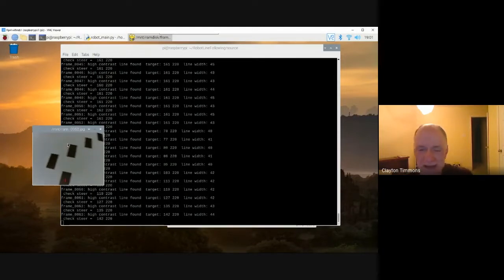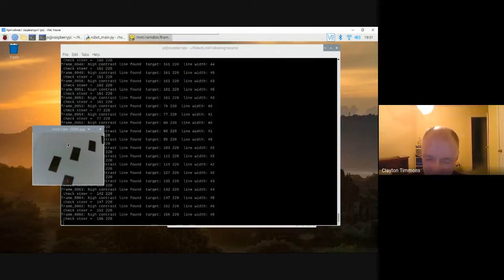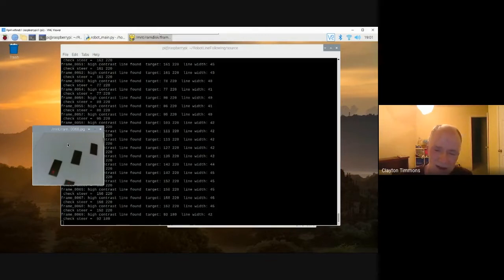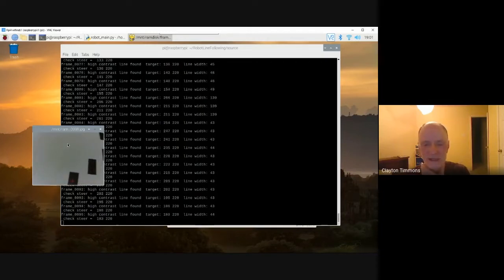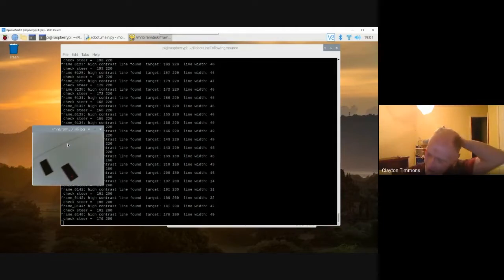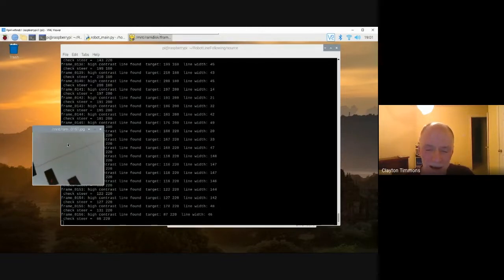And I'm very curious because I'm seeing, a lot of getting this to work correctly is the steering algorithm or tuning. When I see this, how hard do I steer? Those kind of things. And one of the things I'm working on right now is it does go through this S-gap, S-curve, but it's incredibly jerky. You can actually see it basically hop from segment to segment to segment. So that's the next thing I'm working on, is putting some smoothing in there, basically the precursor path planning to smooth that out so it's not so jerky through that.